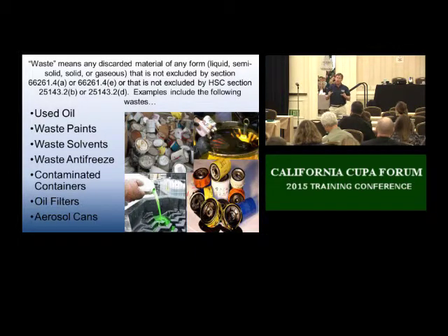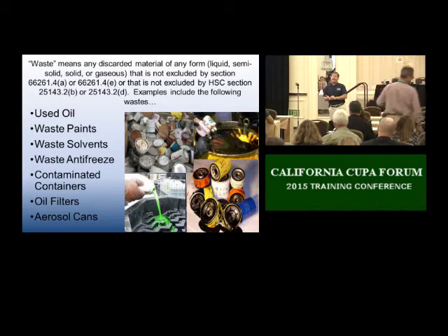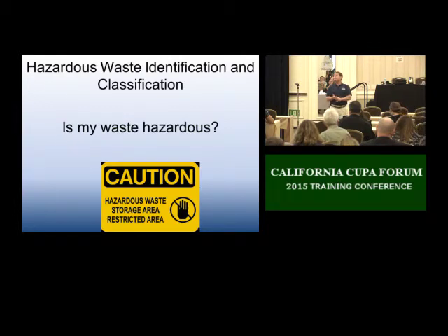And when I test my waste, there is something in the standard, Title 22, Appendix 10, that says you have an 80% degree of assurance that 80% of the time, the waste that you regularly produce using the same process is or is not a hazardous waste. You can determine that using a calculation called student T analysis. So what if I test that 14 tons quarterly every time I send it out?